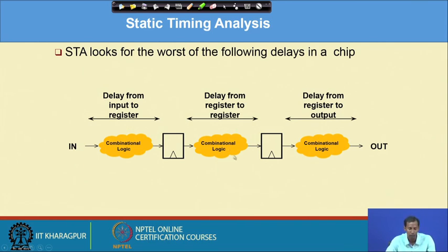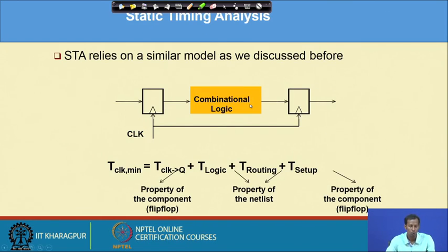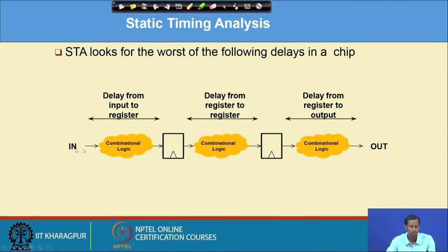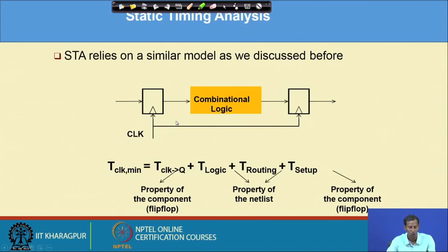Okay. So now we have to calculate the timing analysis for this. So, how can we calculate this STA? Whenever there is an input to the registers, then register to register, then register to the output. Inside this register to register path, whatever the logic is will be considered as the minimum timing requirement for the corresponding clock.